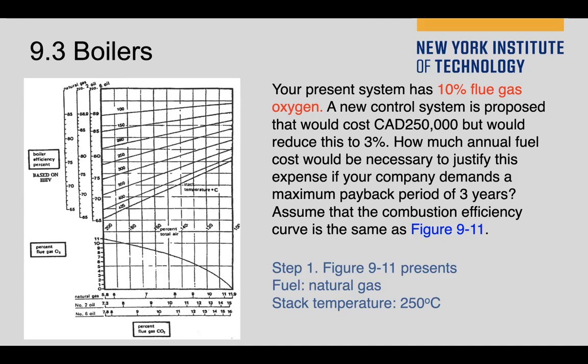But be careful, 0 sometimes may not be the best, because if you have a high volume of fuels, you burn the natural gas, but you do not provide a sufficient percentage of oxygen, it also wastes the fuels. It's an incomplete combustion. Okay. But if you exceed with a high percentage of fuel gas oxygen, it's also another kind of waste. It's about the energy you use to drive the pump to bring the air to your system.